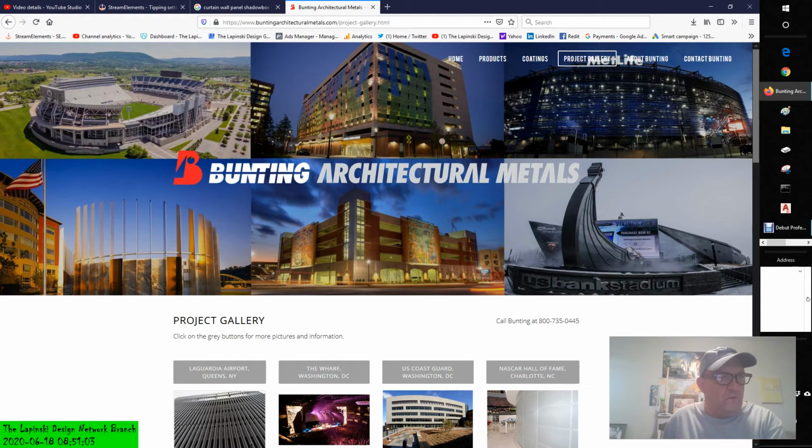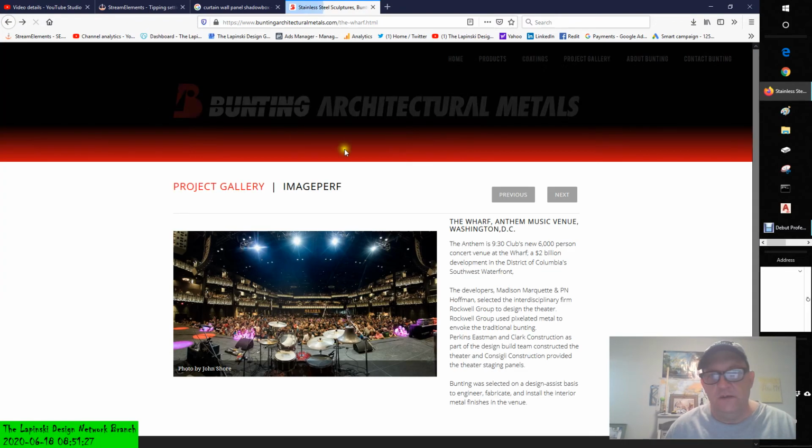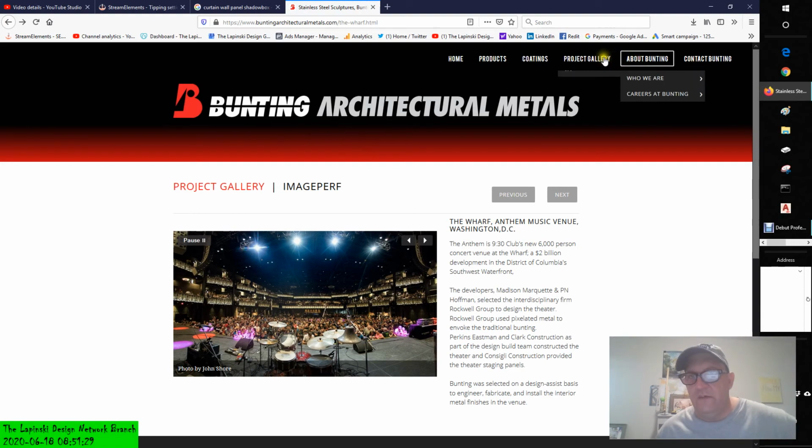The louver fins are arranged in a parametric array within the generic model, and then the generic model is placed in the panel. The edges of the louver array are constrained to the reference planes in the panel. This parametric louver curtain panel is downloaded from RevitCity.com. So, again, we can go on, and this is a really good website. As you can see, they're an industry leader.